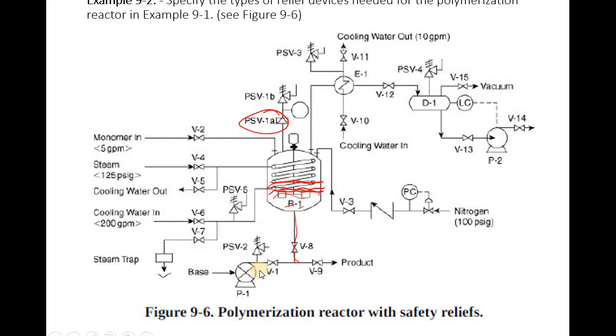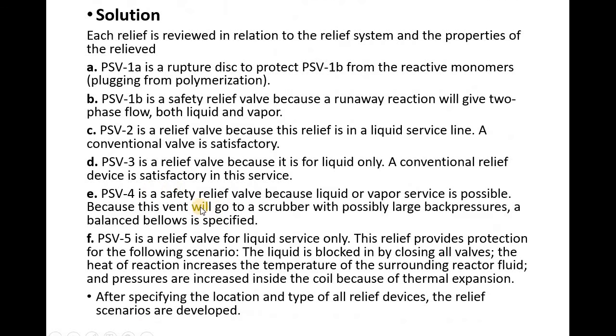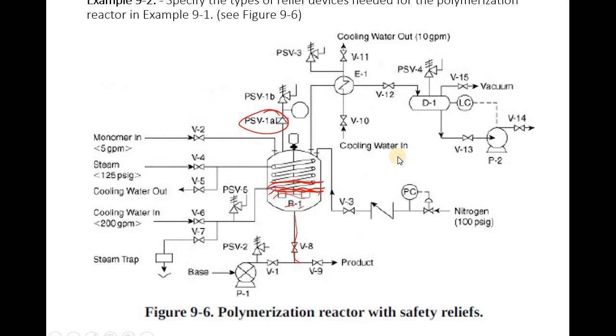Whereas PSV3 is up there, where I have cooling water. Because it's water, it's only a relief valve. PSV4 is a safety relief valve, because liquid or vapor service is possible. And let's see what PSV4 is. PSV4. Did you find it?